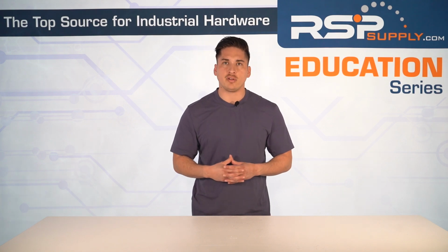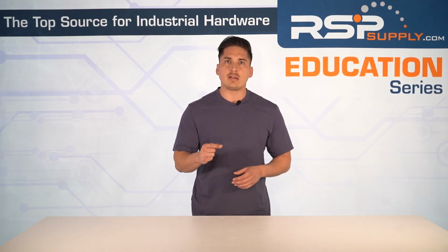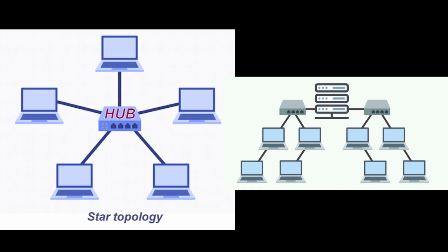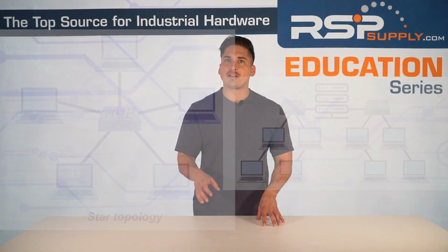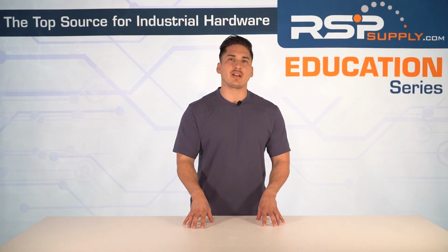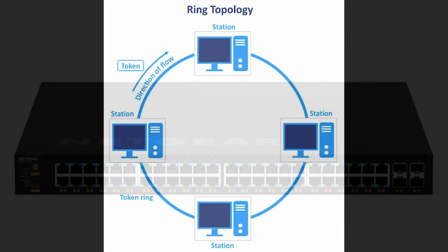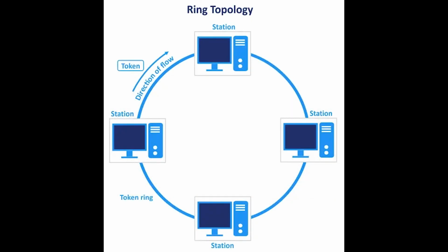In terms of topology, industrial Ethernet often uses a star or a tree structure where devices connect to a central switch or set of switches. This makes troubleshooting easier and allows for flexible expansion. With managed switches, you can also set up ring topologies using protocols like RSTP or DLR to add redundancy, so if one connection fails, the network keeps running.